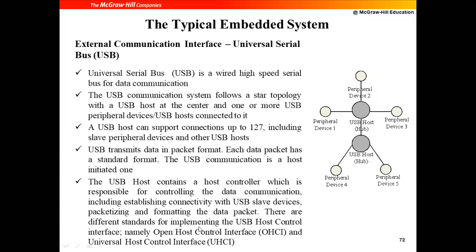There are different standards for implementing the USB host control, namely the Open Host Controller Interface and the Universal Host Controller Interface. These are different protocols that can be followed. Based on the protocol followed, one decides the data rate, how the packetization is done, what the start bit and the end bit should be. Everything is decided by this protocol and controlled by the host.